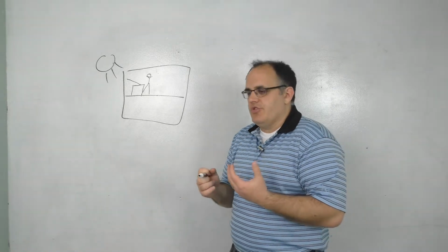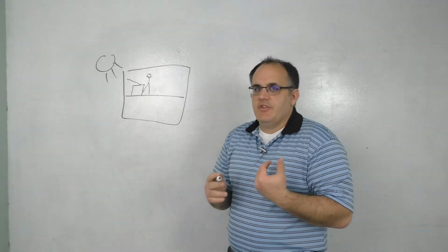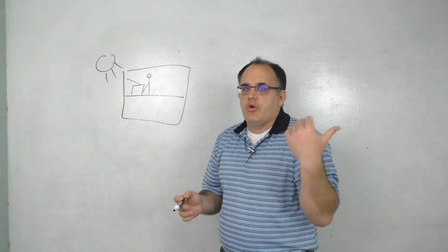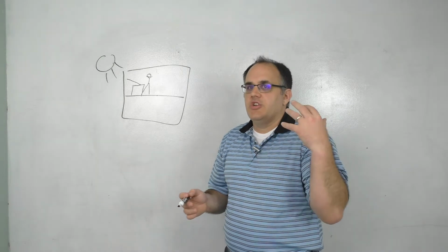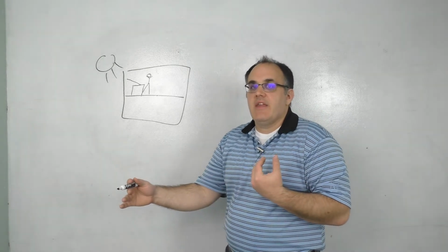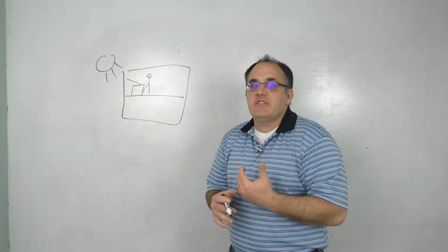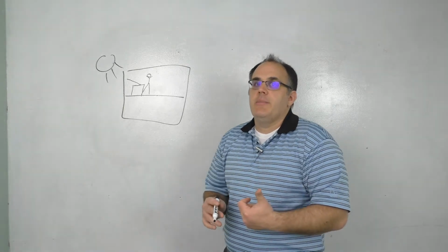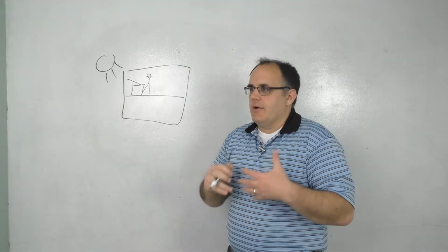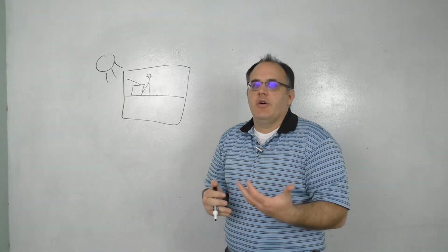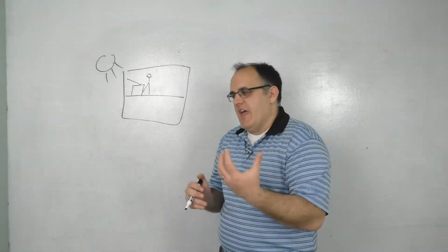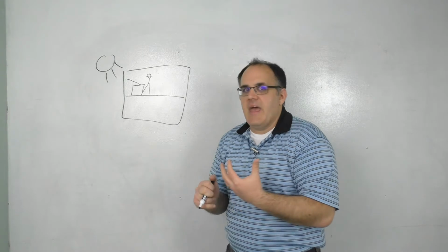So what a lot of folks will do is they will try to avoid hitting that peak demand, especially since when you turn on equipment, that's when the largest demand draw tends to happen versus when the equipment is operating. That's why things like VFDs are so attractive, not only because they allow you to use equipment efficiently, they also allow you to use equipment with soft start. So you're not just slamming your kilowatt, not slamming your demand.